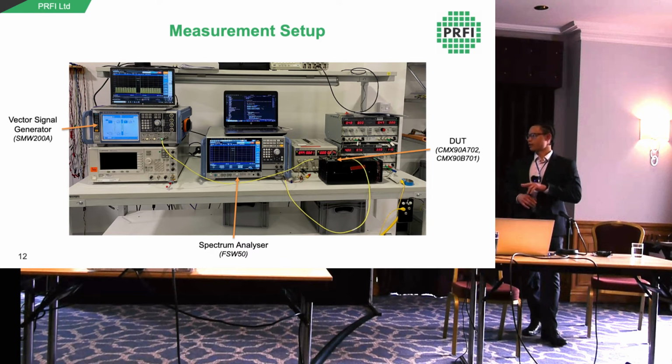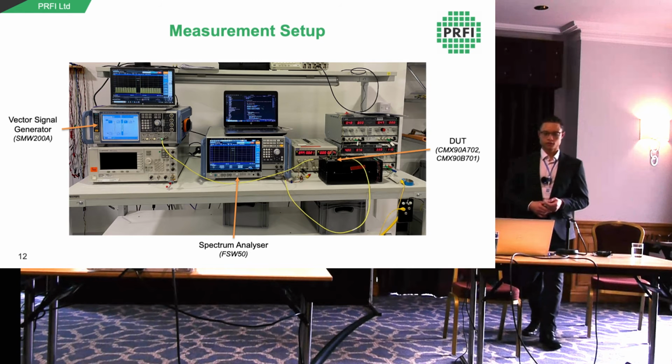The instruments can be connected if you want to make sure that any changes on the spectrum analyzer are reflected on the signal generator, so that the signal you're generating is always aligned. But in practice, we set custom notch widths and channel bandwidths to align more with the settings that we had in simulation, which weren't quite the defaults.